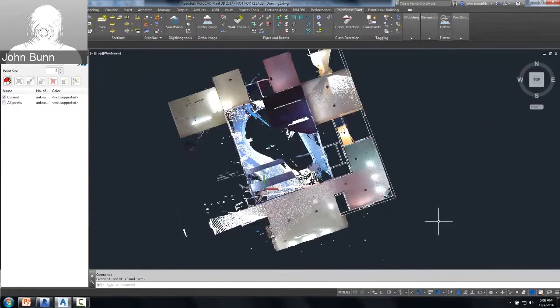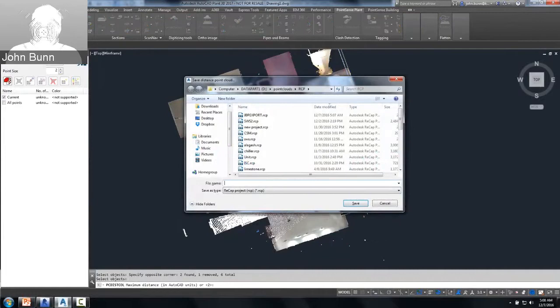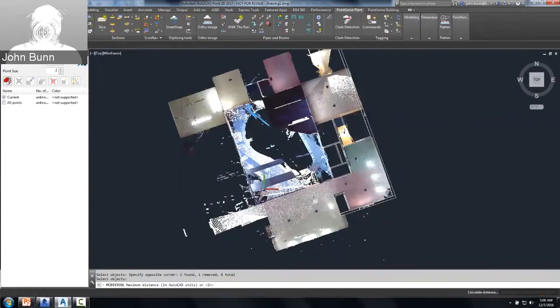So what I did is I went ahead and brought in the SAT file. I'm going to use the analysis tool and select whichever solids I want to compare to the point cloud. Now, what I'm actually comparing in this example is a set of cabinets or drawers. So I have those selected. It's going to generate a point cloud once I give it a place to save to, and then, like we did before, change the intensity value to get the deviation results.